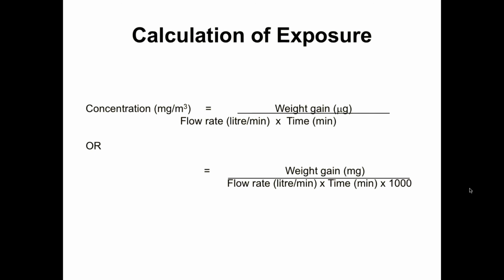For instance, you mentioned before, it's not a lab. You're assembling these in a dusty environment. You're putting together your sampling train in a dusty environment, and so on and so forth. Maybe there's something in the air, some other kind of aerosol that winds up getting on the filter before you get started, in the environment where you're putting together your sampling train. Okay, so that's going to affect any sample train you assemble in that environment.